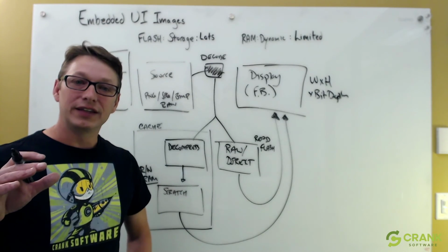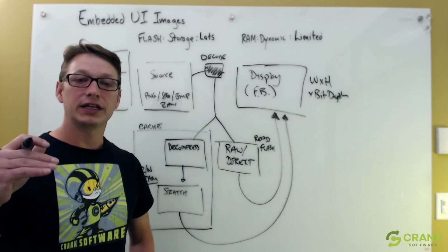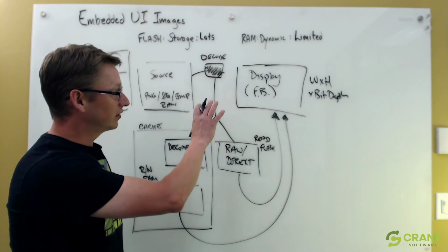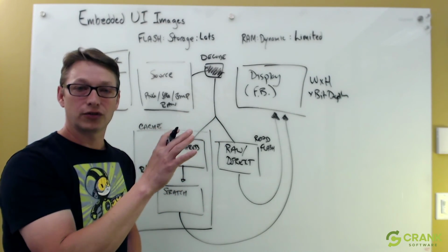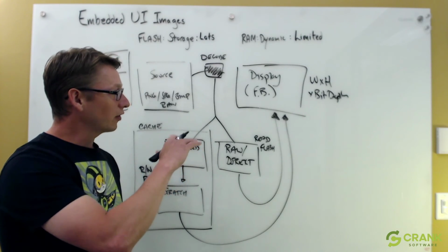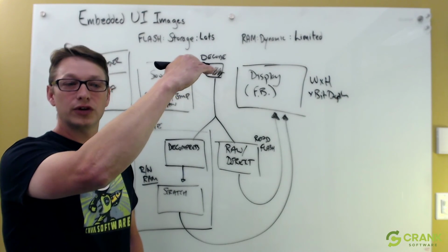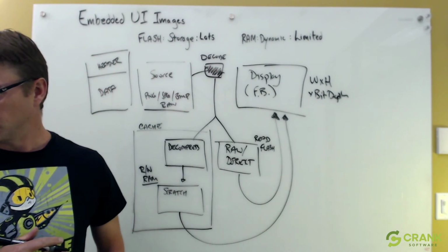What you can't see is how much memory any individual screen is. So Storyboard gives you that ability to identify the resources that are used on various screens, so that you get a better idea of here's my ultimate high water mark, and then here's really my realistic operating high water mark on a screen-by-screen basis.